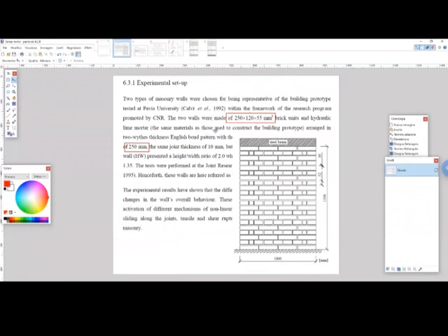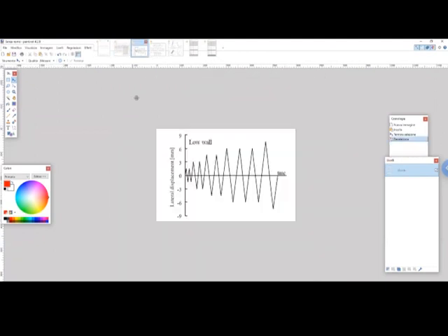These are the dimensions for the bricks that we are going to put here. We are going to do a 2D analysis. This is the entire thickness, and this is the dimension of the wall. So we are going to model the entire structure, and then we are going to model 2 steel beams on the bottom and on the top. Then we are going to apply first a vertical displacement. Then I will show you how to apply a fixed rotation at the top beam when you are dealing only with 2 degrees of freedom displacements in UX and UY. And then in the second stage of the analysis, we are going to apply an imposed cyclic displacement on the top beam.